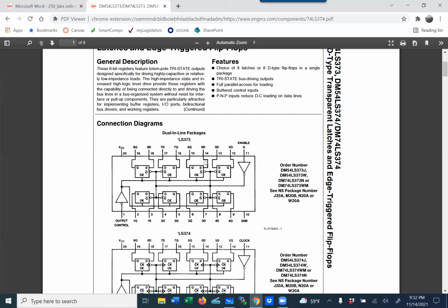This way, you're leveraging the work you did in the previous lab, when it was just deciding if it's time to go green or not time to go green, but kind of selecting the priorities in earlier labs. You take that plus the 555 timer, just build one delay for each lane, and you can create your circuit that way. And it would be a little bit faster to do it that way.